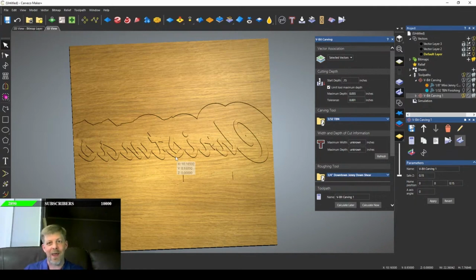Having a perfectly smoothed out spoilboard will allow your material to sit flat onto it. I also highly recommend surfacing your material before you start, and that will ensure that everything is perfectly flat. If it's not perfectly flat on both the female and the male side, you are going to run into fitting issues.